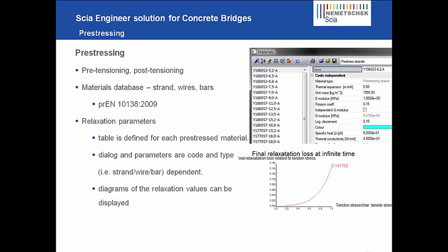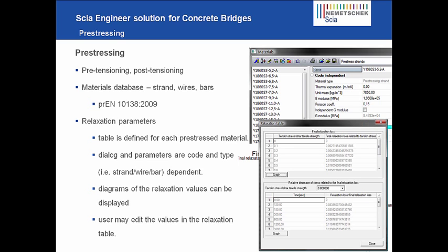And each of these materials contains relaxation parameters. So there's a table for each prestressed material. You can also see and show these values, and these values will be used to calculate the losses in the cables. But it's also possible that you edit them yourself.